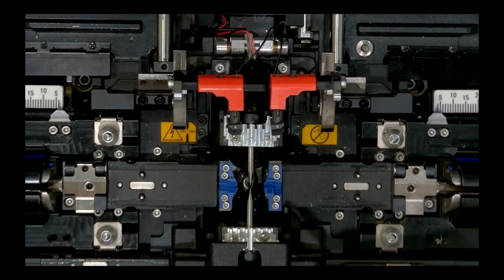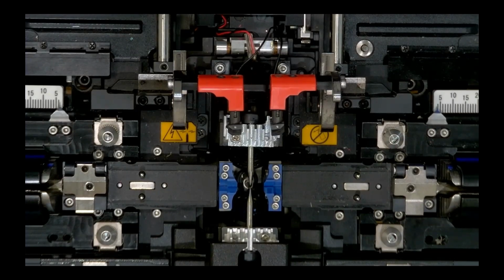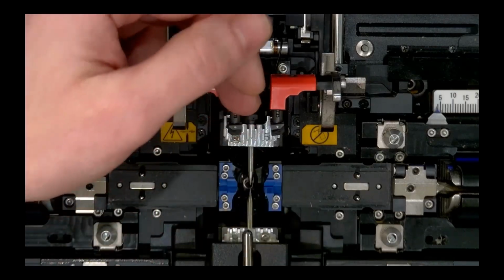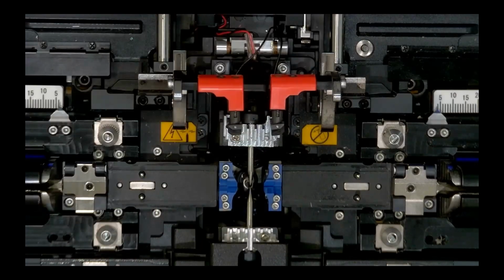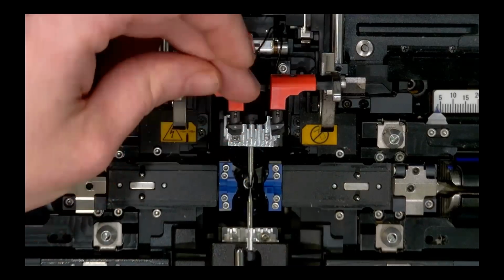However, on the plus models, these electrodes can also oscillate up and down to accommodate larger diameter fibers. Because even if the electrodes are 3 millimeters apart, you can only have a plasma field that's so large. And so you need to physically move the plasma field in order to evenly heat a fiber. And so these plus models will allow you to swing the electrodes up and down, as well as adjust the gap between the electrodes depending on your fiber size.